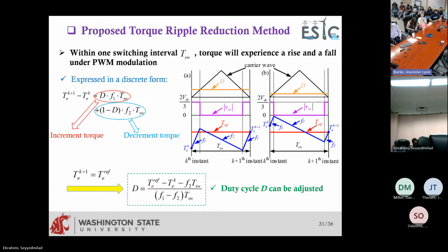You do it by your controller. The controller gets some inputs, gets the value of speed that goes into the equations here, switching frequency, calculations of the torque, and then the controller calculates this. In the controller DSP, it generates the duty cycle and switching signals for the next switching interval.